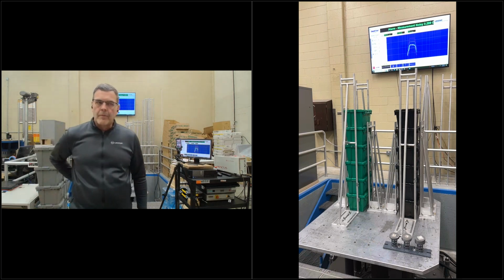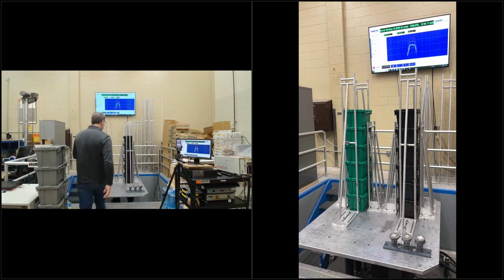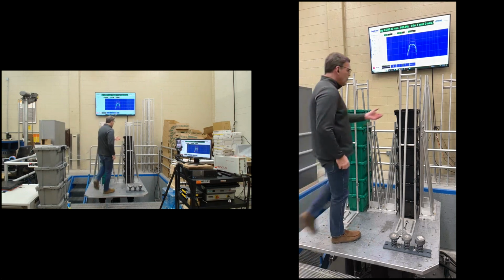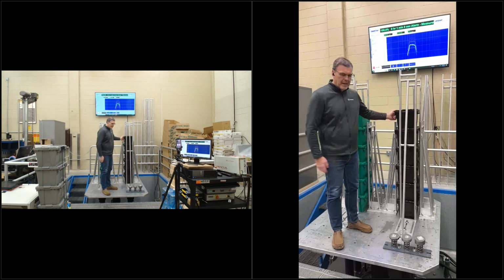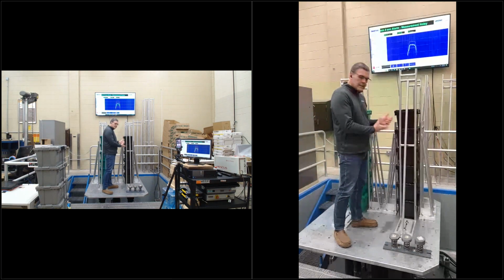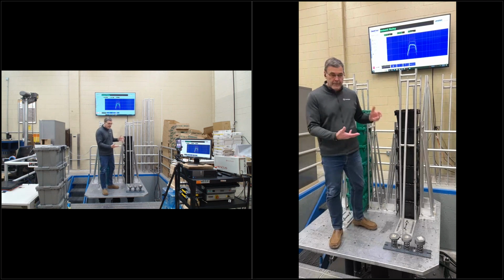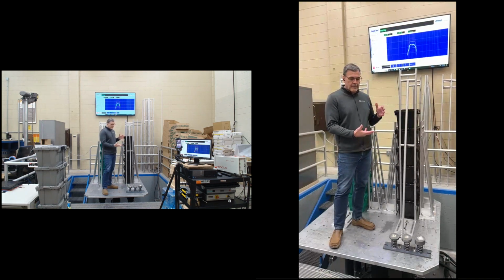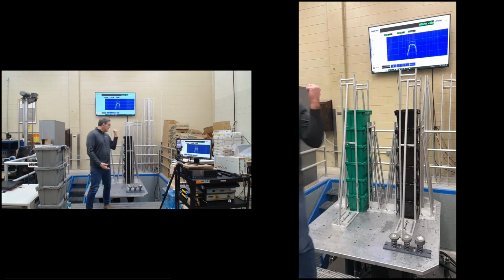The other thing that you don't get, at least if you're talking about individual layers, a big concern, now these are plastic containers on here, but a big concern if you're shipping corrugated, or even maybe plastic, is something called dynamic compression. As vibrations occur going down the road and you have a stack of packages or loads, especially if they're not unitized all that well, they might respond individually, just like these are.